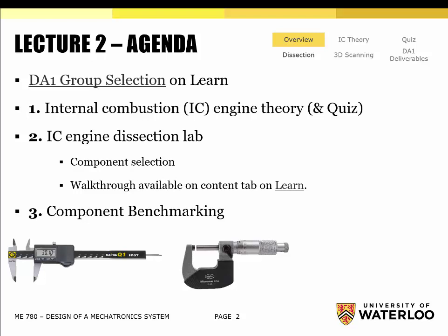However, if you want to redesign the piston pin, the part that connects the piston to the connecting rod, and you say, oh, the diameter of that is not important because I just don't want to measure it, that obviously is a critical oversight. It needs to interface with the piston, and that diameter is very important from a thermal expansion perspective and from a friction perspective. All those things are important. So you're using your judgment there on what you need to measure. Pictures always help. Okay, a picture is worth a thousand words, so do that.